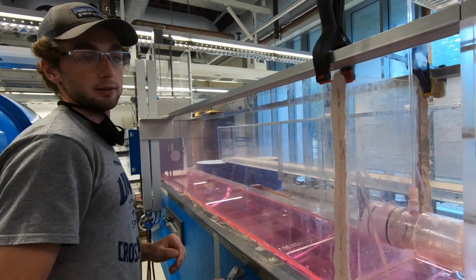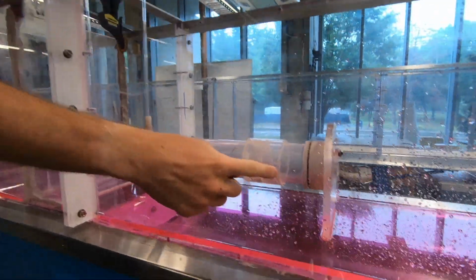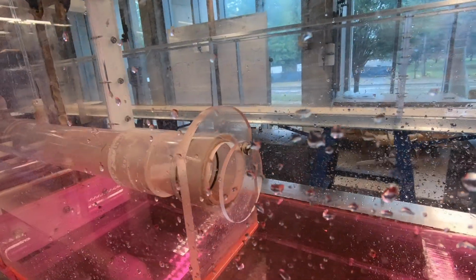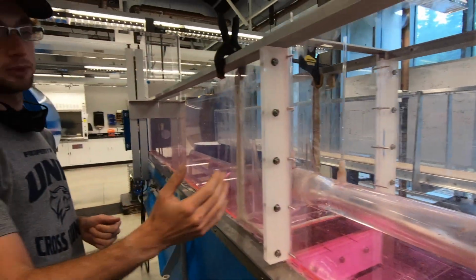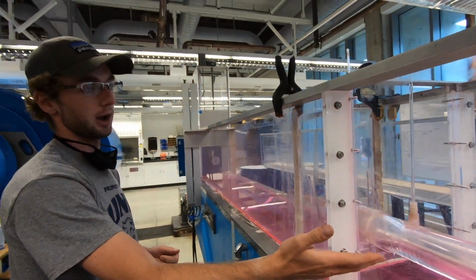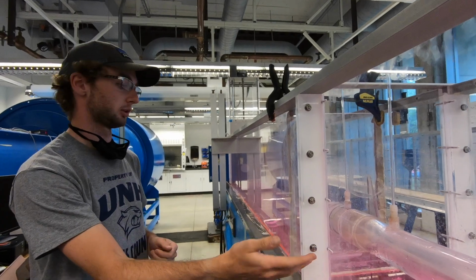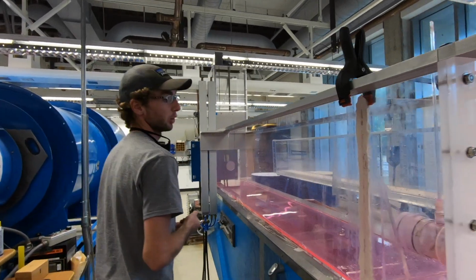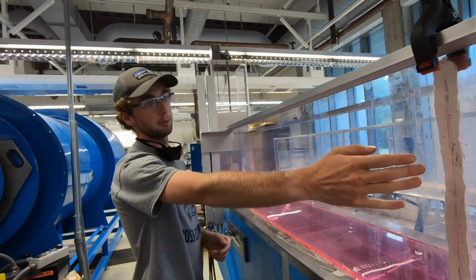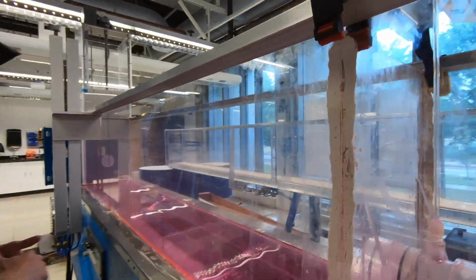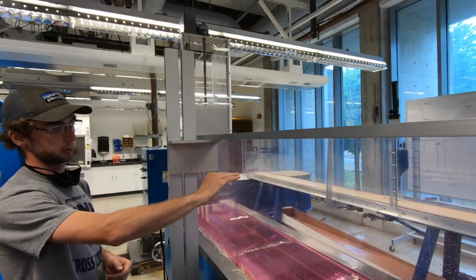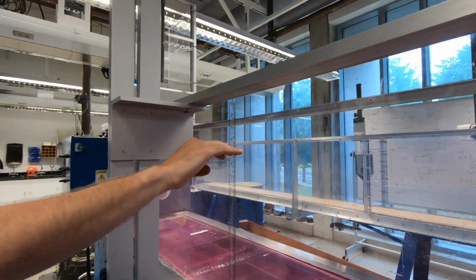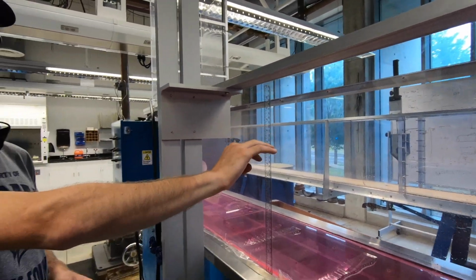In this case we have a valve here at the end so that we can block off the end of the flow so that we maintain full pressurized flow in the Venturi and have no open channel flow taking place. When we're running this, our water is going to back up behind this wall, and for each trial we're going to keep a consistent level of water within that trial. We're going to be starting at 13 inches and going down in increments of 1/2 inch.